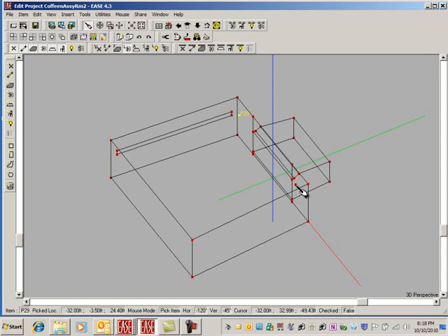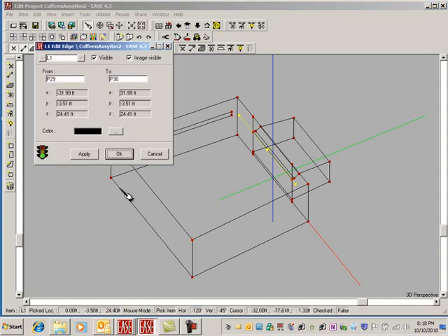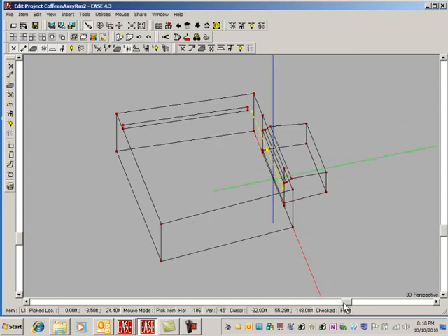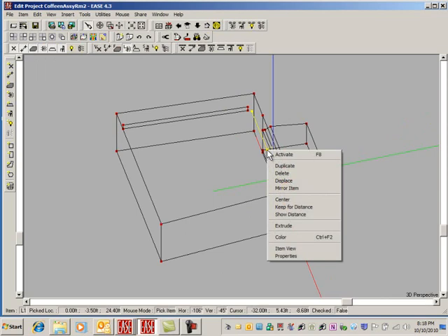It's called L1. We don't want a line there. We could simply right mouse click and extrude this line. We could extrude it in polar coordinates. Horizontal would be 0 because it's looking down the 0 direction. This is 0 this way. Vertical would be up 10 degrees, and the distance is 12 feet. Say OK. There's a face right here.